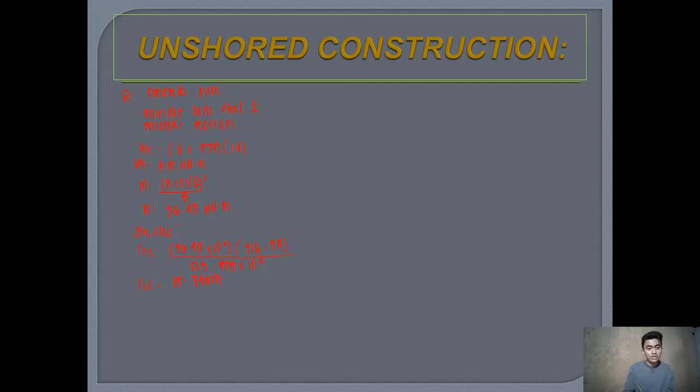But take note, this is your stress at the topmost part. So this is your transform stress for concrete. So divide this again by the value for your modular ratio, which is 8. FC now is equal to 15.74 divided by 8, 1.97 megapascal. All right. Then the next one for Fs,